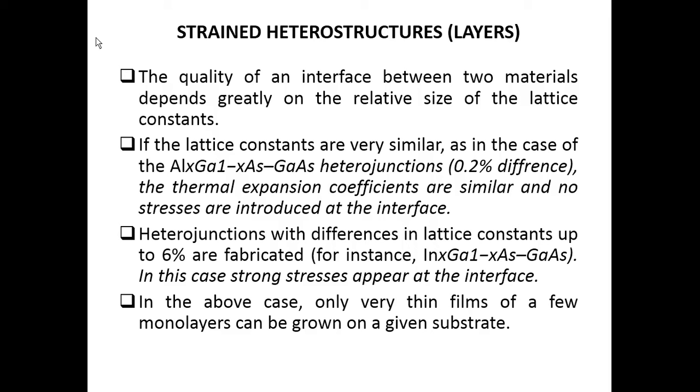aluminum gallium arsenide, where two dissimilar semiconductor materials are joined: aluminum gallium arsenide, which is n-type or a lightly doped one, and gallium arsenide, which is an intrinsic semiconductor having very low impurities, with no dopant added. Such heterostructures make a modulation doped one. We have discussed the different features which that particular device exhibits.